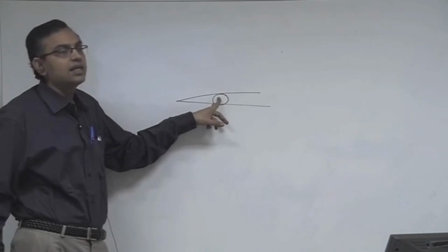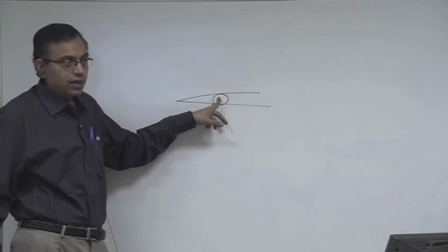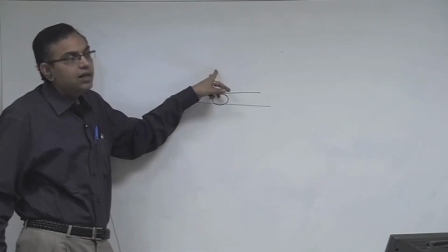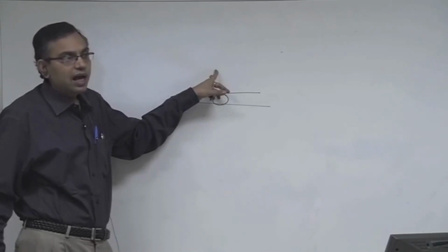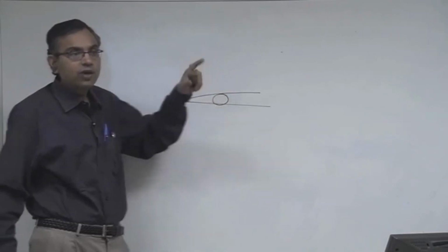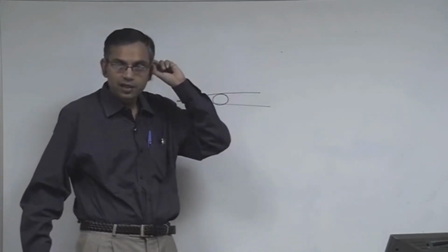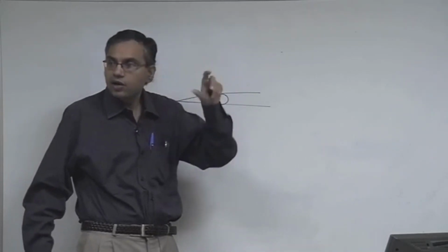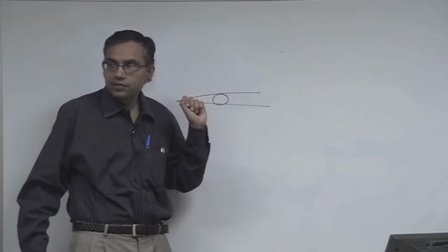If we neglect this region altogether, the problem is that we neglect the viscous effects altogether, and mathematically we bring down a second order PDE to a first order PDE, because when viscous effects are not considered the Navier-Stokes becomes a first order PDE, the second order effect is not there.